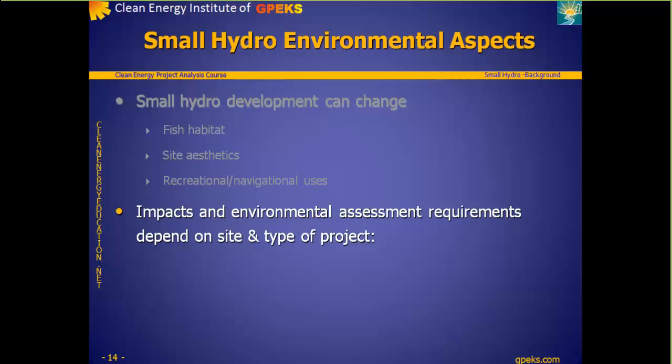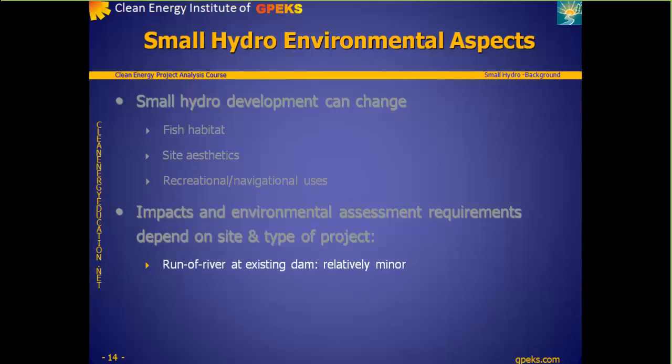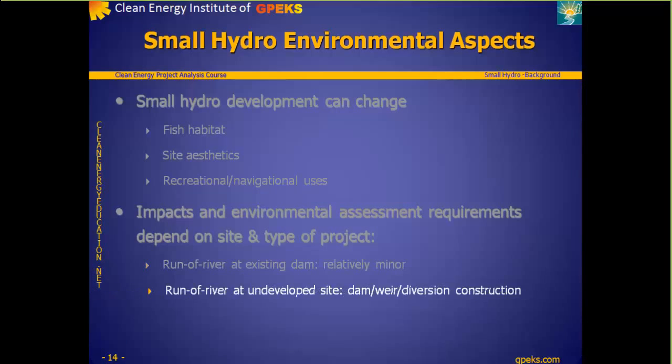Fortunately, most small hydro systems are run-of-river plants that do not cause significant flooding. The creation of new reservoirs is rarely financially feasible for projects of this scale. The creation of a head pond, or small reservoir meant to smooth flows, may cause minor flooding, but this will generally be limited to rapids just upstream of the dam. Sometimes small hydro projects make use of an existing lake or reservoir for water storage.